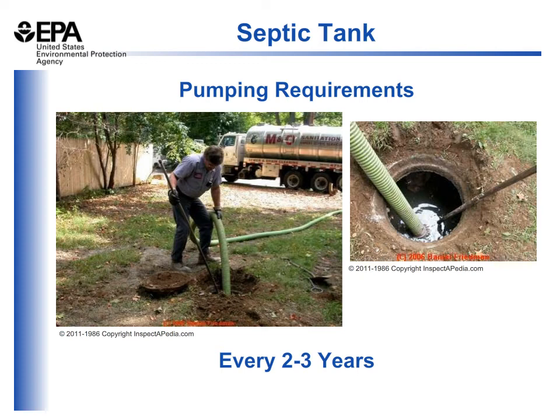Septic tanks need to be pumped on a regular basis to remove the solids before they accumulate to a level where they can make it through the outlet pipe and out to the leaching facility. For a typical home, a septic tank should be pumped once every 2 to 3 years. If the home has higher occupancy, or if the septic system is connected to a business with a higher water flow or a higher pollutant load, then pumping should be done on a more regular basis.